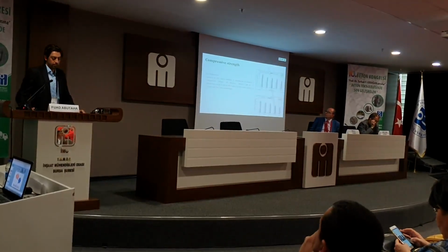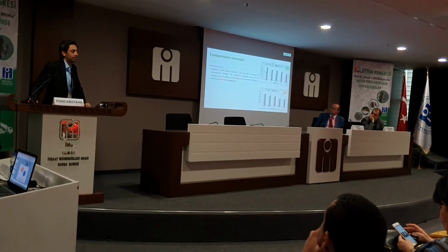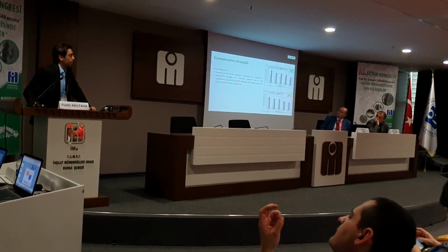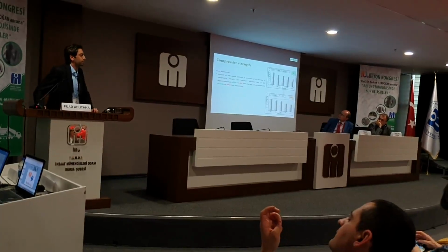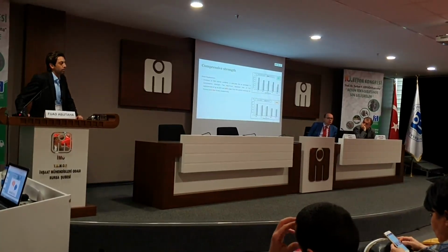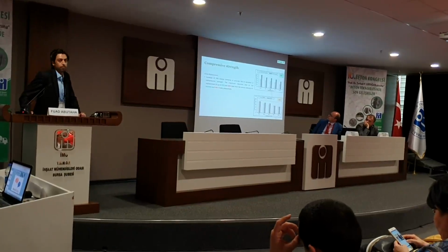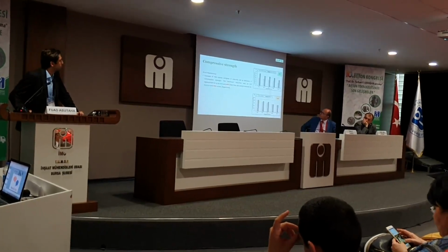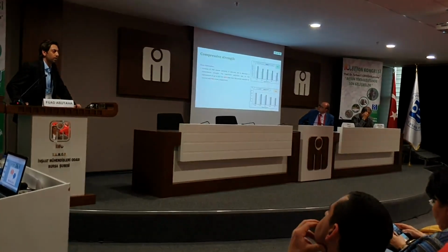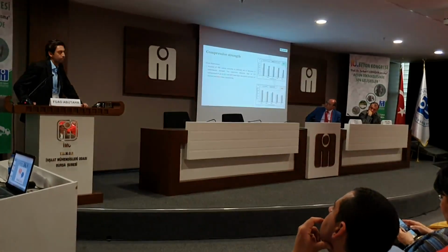So the results for the compressive strength: the first observation is that when we directly replace with POC coarse aggregate, we had a reduction in the compressive strength. The compressive strength decreased with the increase of the replacement level. The maximum reduction was at full replacement, which registered a value of 30% lower than the control for normal concrete, and a 40% strength decrease for the high strength concrete.